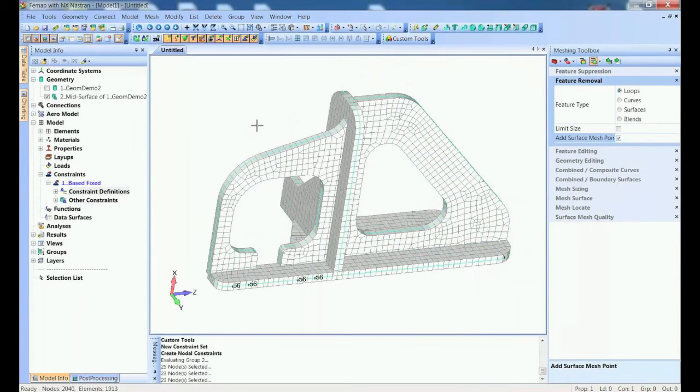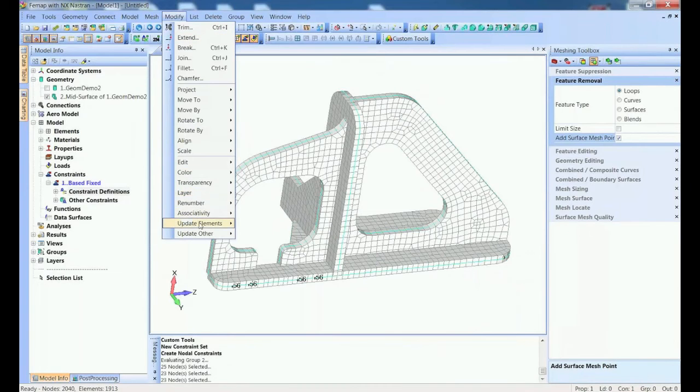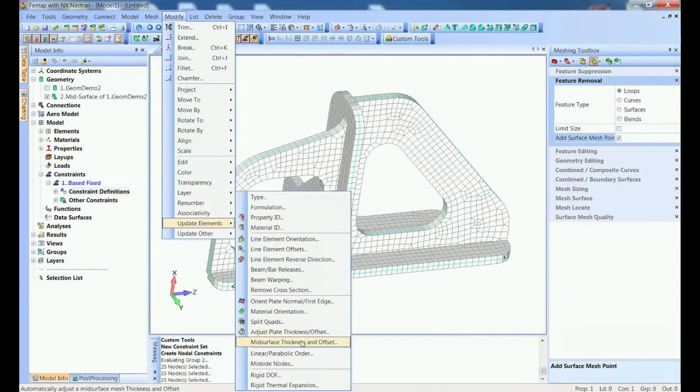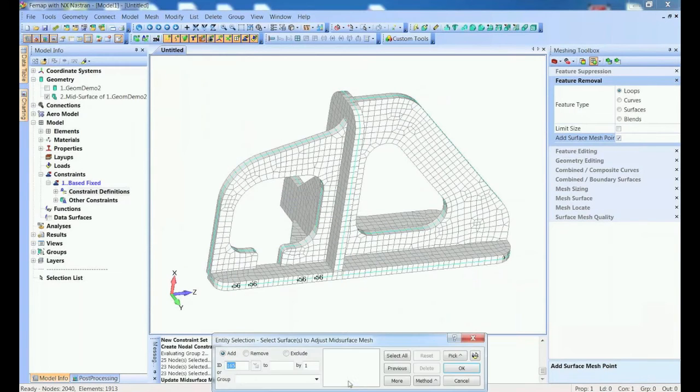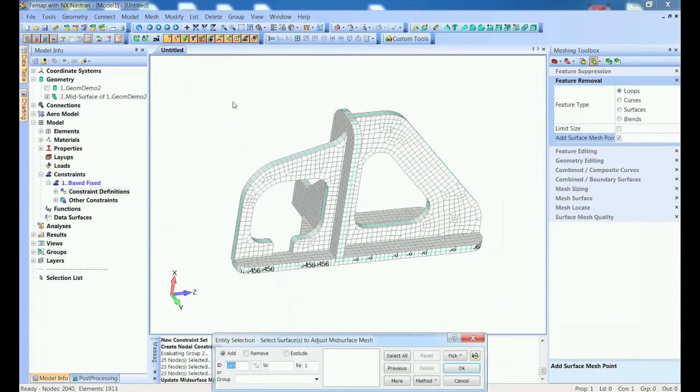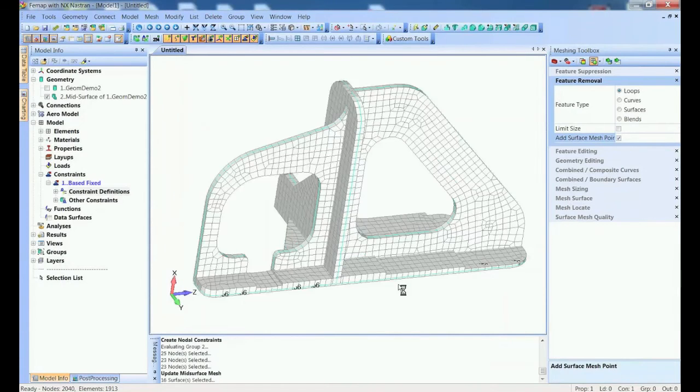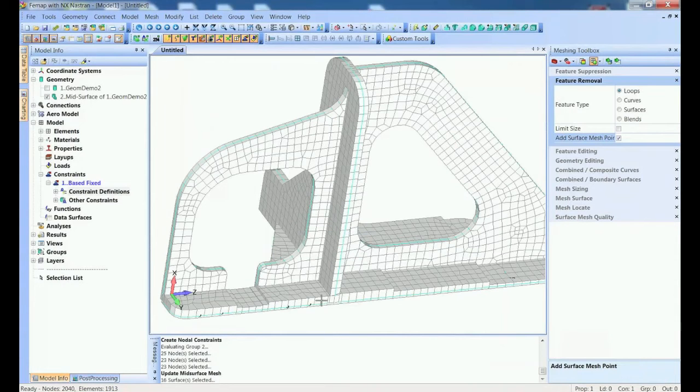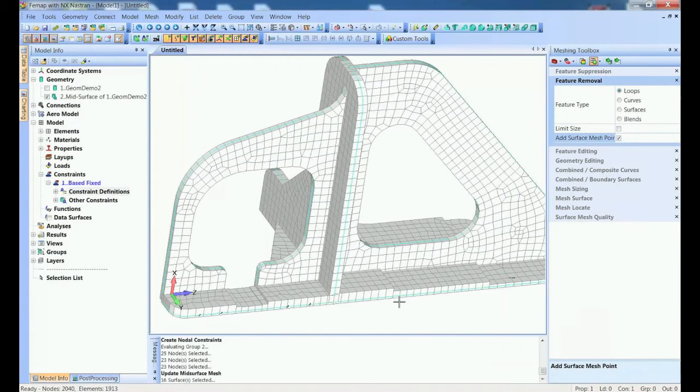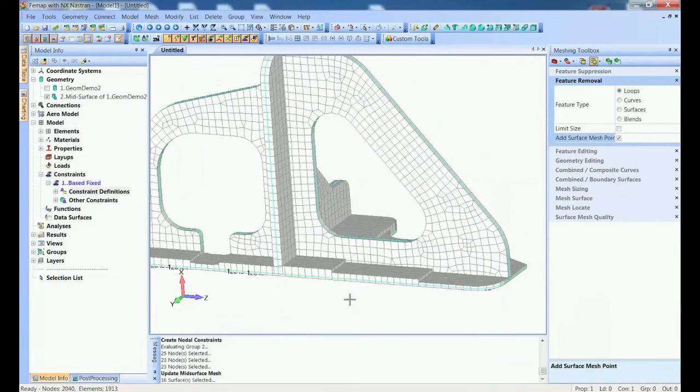All right, so now everything is a uniform thickness. So let's turn the thickness on so you can actually see we have the 225. And we're going to run the update command. So this is what I was talking about a while ago. Instead of having a properties, we're going to run the update. You can see what it does. It's just the thickness across the offset. So you can see as all the elements now have their own specific thickness changes.